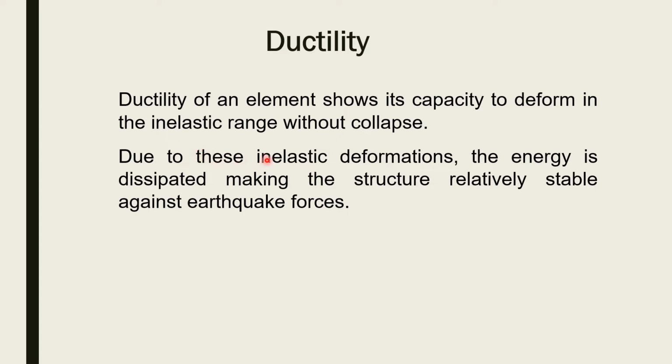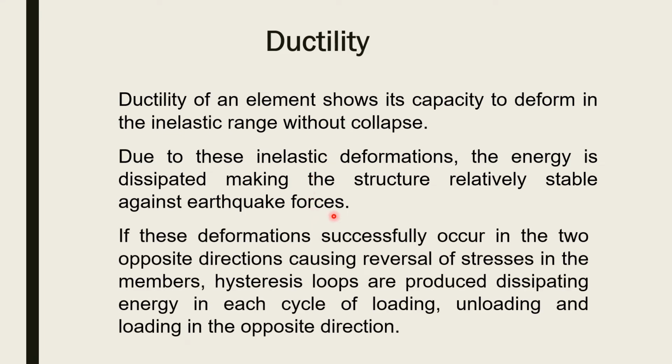Due to these inelastic deformations, the energy is dissipated, making the structure relatively stable against the earthquake forces. So ductility causes energy dissipation and makes the structure stable. If these deformations successfully occur in the two opposite directions, causing reversal of stresses in the members, hysteresis loops are produced, dissipating energy in each cycle of loading, unloading, and loading in the opposite direction.